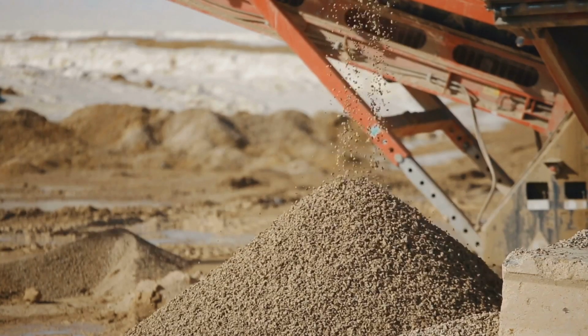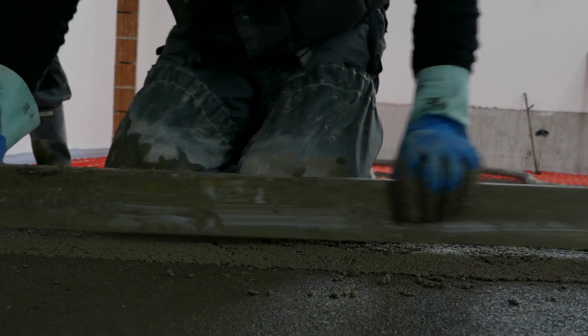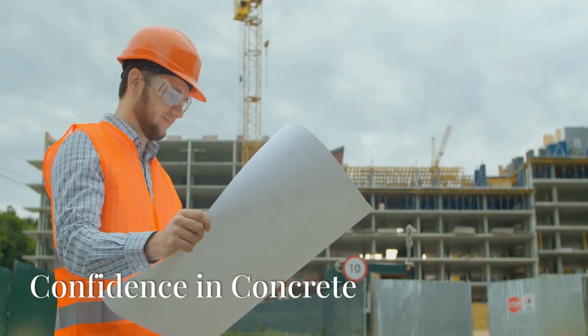You'll also see markings for control joints spaced every 4 feet. Additionally, there's a note specifying the use of compacted gravel for the base, to a depth of 4 inches. This tells you everything you need to know to build a sidewalk that's the correct size, slopes properly for drainage, and has the necessary structural support.